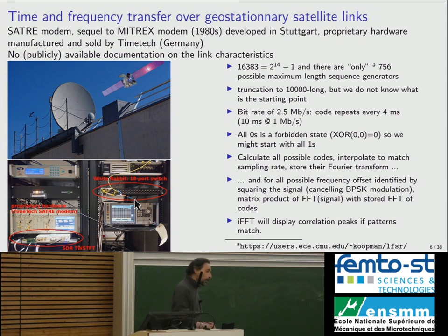So two-way satellite time and frequency transfer was initiated in the 1980s, I believe 1983, with a first paper by a German author from Stuttgart who implemented, well, actually, if you look at the papers from 83, and Andreas Bauch has been very helpful in identifying these original papers, you see that the Mitrex modem was implemented, and the author refers to GPS as a pseudo-random sequence that is transmitted over radio frequency waves, and by correlating the signal, we're going to recover the time.